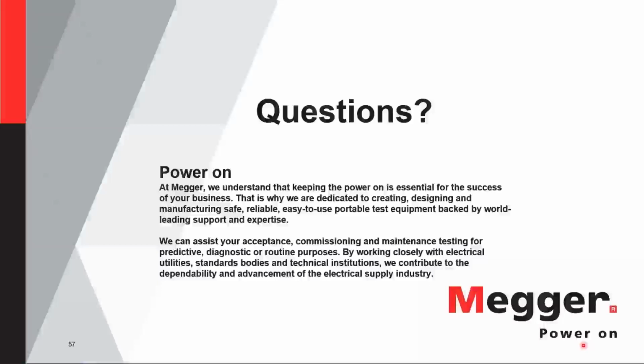All right, thank you. Next question, can we apply standard D877 or D1816 when testing current transformer oil? Yes, those standards are for insulating liquids. So basically any oil or any liquid that you are using for insulation in any electrical equipment, you can use these standards to perform the breakdown test. So the answer is yes on that one.